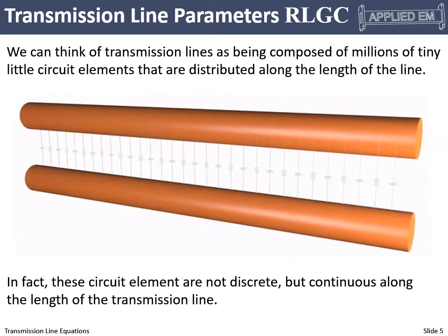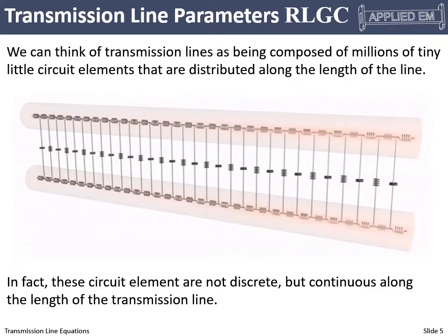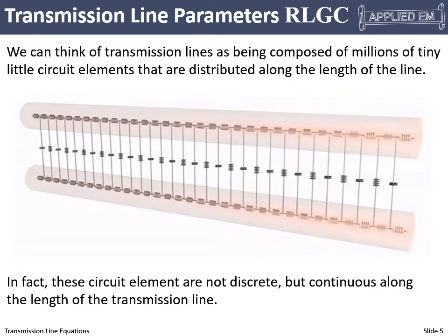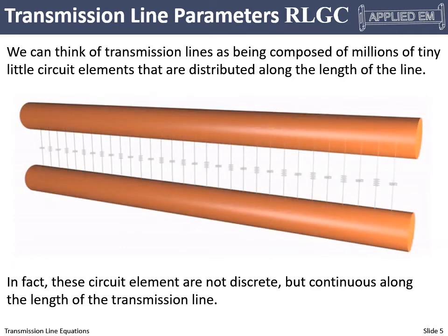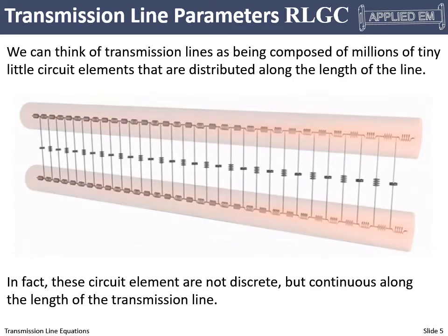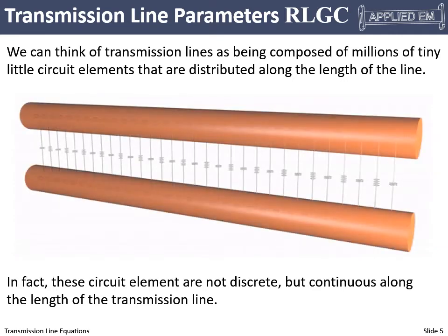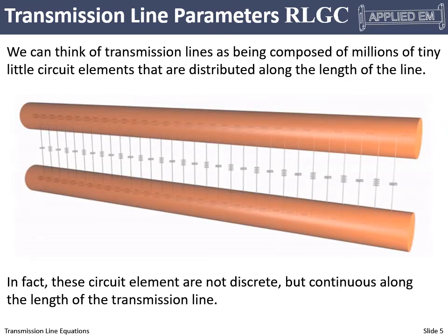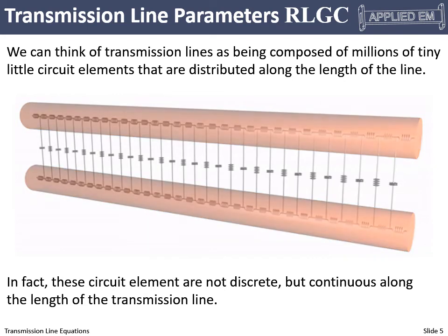At its simplest, a transmission line is two pieces of wire. Well, we know that there's some resistivity in the wire, and if there's any sort of dielectric between the wires, there may be a small amount of conduction between that. And the two wires form somewhat of an inductor and somewhat of a capacitor, and we have all of these different RLC properties really uniformly distributed across this transmission line.